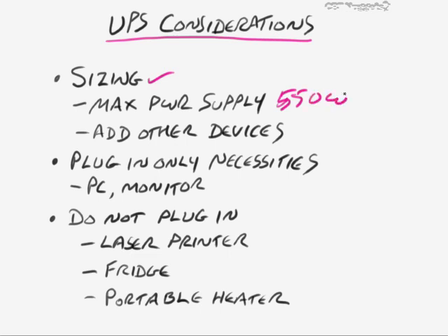So if my power supply is at 550 watts, and I've got a monitor that maybe needs 50 watts, then I've got a total need of about 600 watts, and I have to give myself several minutes of uptime. So if I get a UPS that's exactly 600 watts, I'm probably only going to be up for a few seconds before the battery gets depleted, maybe a couple minutes. So what we'll need to do instead is to get an oversized UPS, at least compared to our total watts that we need.